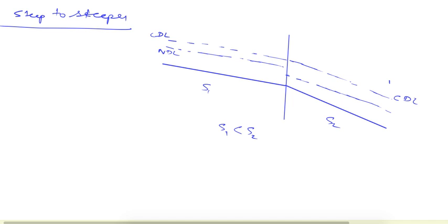Now the control section will again come into use. As we know, the upstream is the control section for a supercritical flow. So whatever change is happening here will not affect the supercritical flow which is happening before this section, but it will change the flow which is happening after this control section, because the upstream is the control section for supercritical flow.